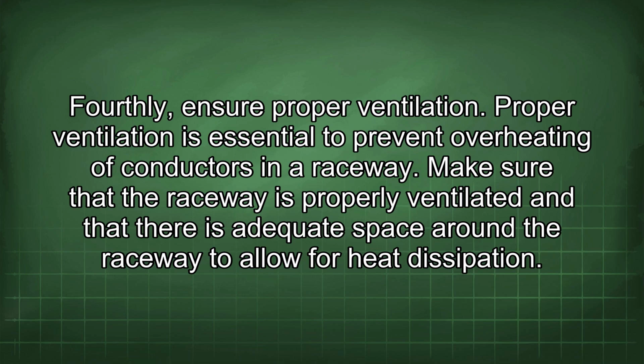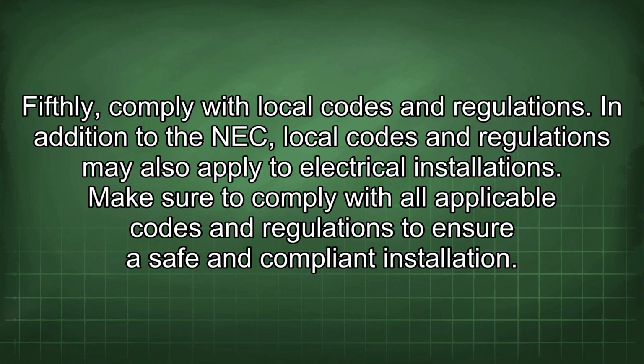Fourthly, ensure proper ventilation. Proper ventilation is essential to prevent overheating of conductors in a raceway. Make sure that the raceway is properly ventilated and that there is adequate space around the raceway to allow for heat dissipation. Fifthly, comply with local codes and regulations. In addition to the NEC, local codes and regulations may also apply to electrical installations. Make sure to comply with all applicable codes and regulations to ensure safe and compliant installation.